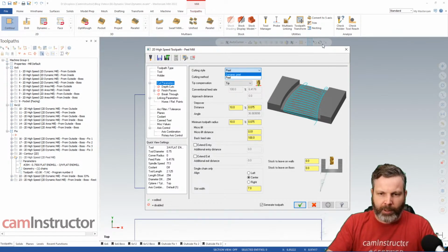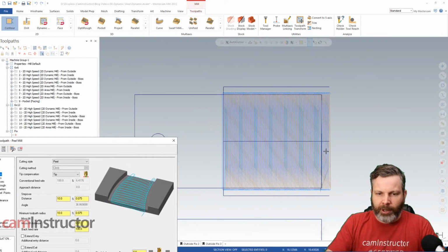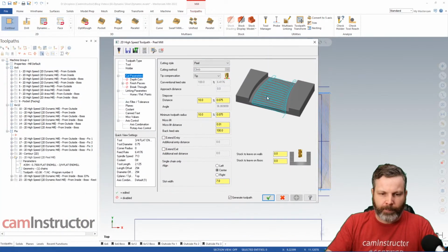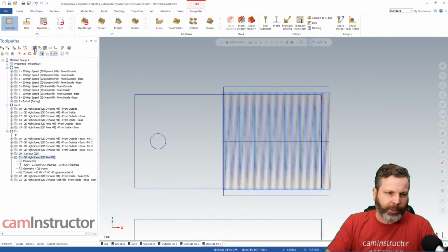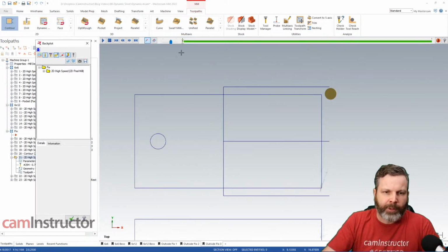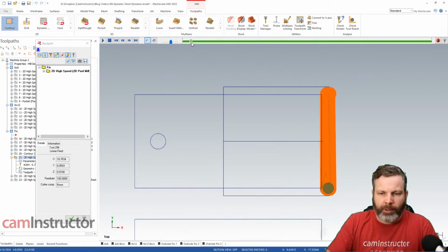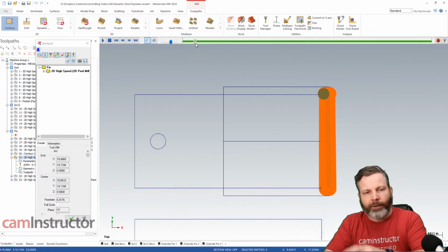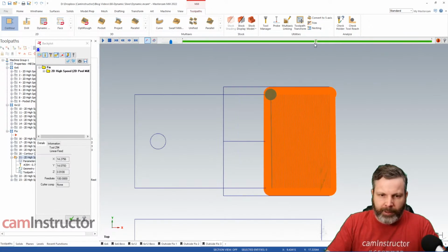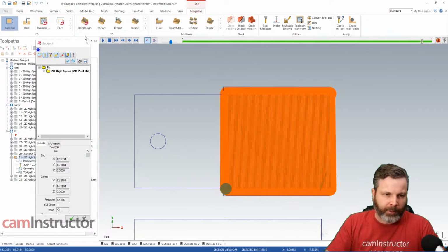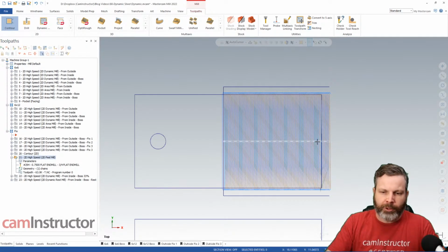And I've just got basically a line drawn in right here at the middle. This is the geometry I've changed for this peel. I basically gave it a width, and we can extend or shorten if we needed to as well. So what you're seeing with the peel is basically the same thing as contour. You're going to see a cut or a retract or reposition, and then the next step over. The added benefit of this peel mill is all I had to do was draw a line.